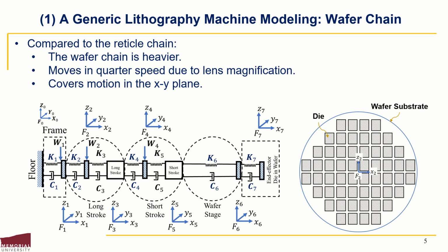It's noteworthy that the wafer stage has 6 degrees of freedom and therefore is capable of realizing in-plane motion in the X, Y, theta Z directions, and out-of-plane motion along Z, theta X, theta Y directions. The in-plane motion takes place during still and scan portions of the lithography process, while the out-of-plane motion maintains focusing and leveling of the wafer during that process. Both the in-plane and the out-of-plane motions are coupled. Therefore, 6 degrees of freedom analysis must be carried out.